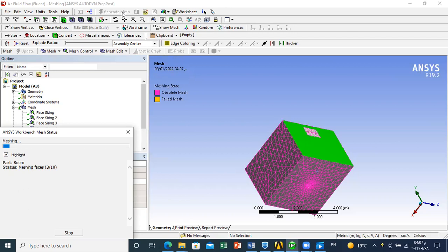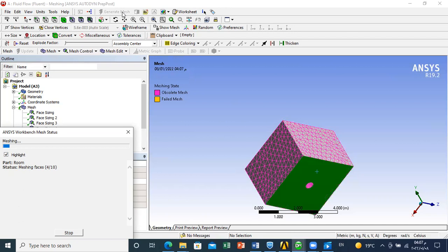In general, we recommend aspect ratios near the walls, a maximum ratio of 10/1, and far from the walls 5/1. Now we can accept larger ratios, but it's recommended to remain in this range. Let's say a maximum below 10 will be fine.